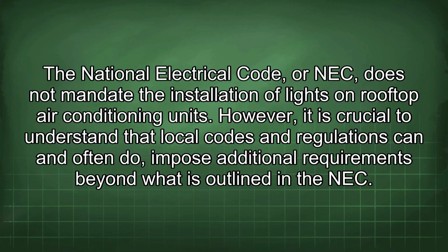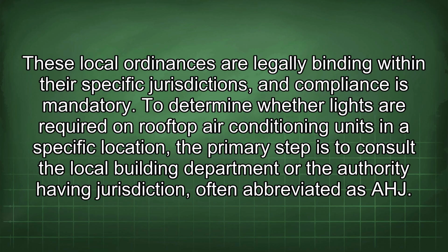The National Electrical Code, or NEC, does not mandate the installation of lights on rooftop air conditioning units. However, it is crucial to understand that local codes and regulations can and often do impose additional requirements beyond what is outlined in the NEC. These local ordinances are legally binding within their specific jurisdictions, and compliance is mandatory.